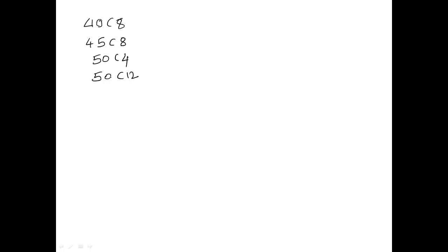Now, if you come to the manufacturing of shafts, shafts are generally manufactured by hot rolling, and finished to size by cold drawing or turning and grinding. So the rough shafts are produced by hot rolling. Next, if you need the required size and surface finish, surface finishing is done with the help of grinding.